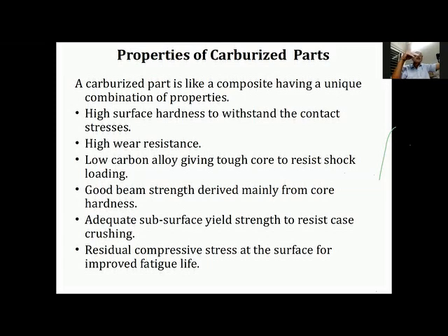Now, when you quench a carburized component, the core has a transformation temperature between 200 and 450 degrees Celsius, whereas the case, because of the higher carbon, starts transforming below 200. Many times, as we saw, if carbon is slightly higher than the optimum level, the martensite finish temperature will go below ambient. But the main thing is the core is already transformed when the case starts transforming.